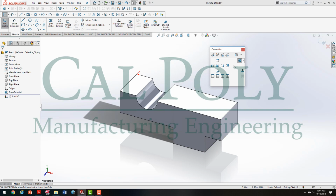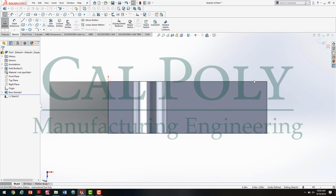Or let's say I didn't know what view I actually had here, such as the top view, which would be this button. I could easily click normal to, it's my favorite view button, and that brings the sketch normal to my view. It's also a Control 8. So when I go ahead, again that's spacebar and normal to, or Control 8 if you like fast keys